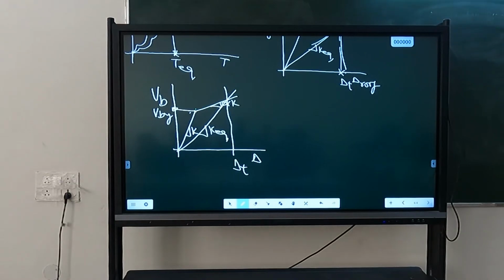The equivalent single degree freedom system of a non-linear multi-degree freedom system will also be non-linear. So the non-linear multi-story building I have converted into equivalent non-linear single degree freedom system. So my single degree freedom system is also non-linear, such that their initial periods are same, mu is same, and hence their equivalent periods are same. The single degree freedom system has been converted in such a way that the initial period was same.